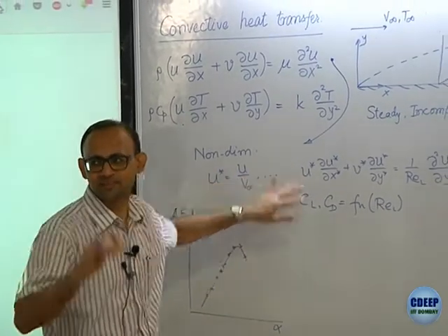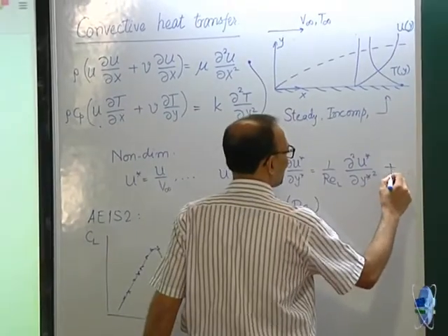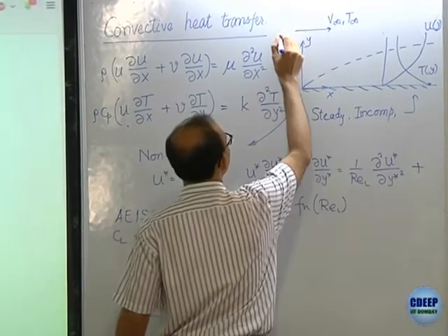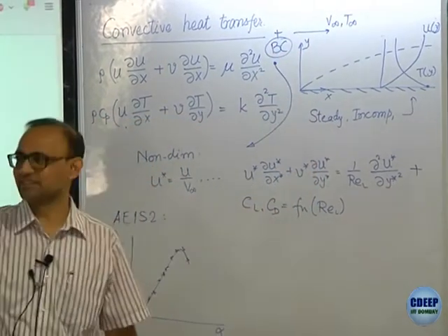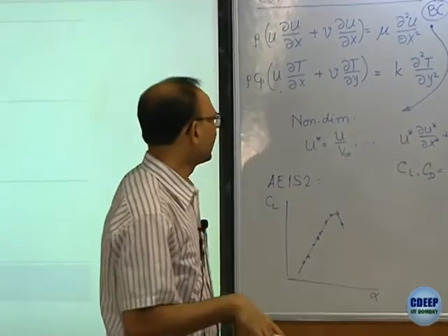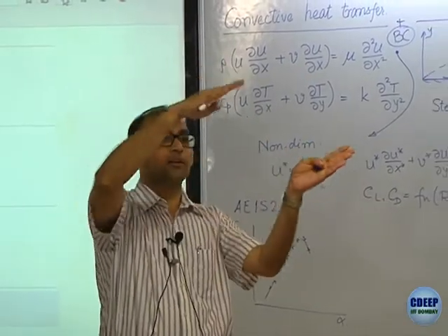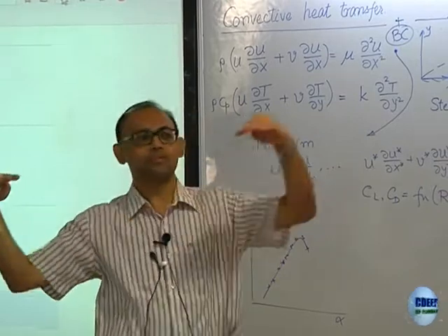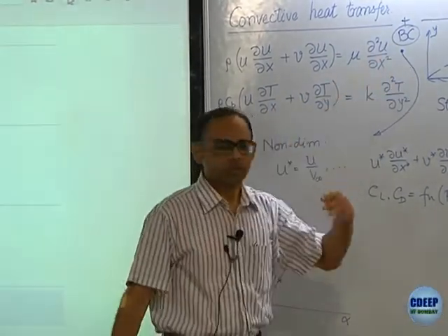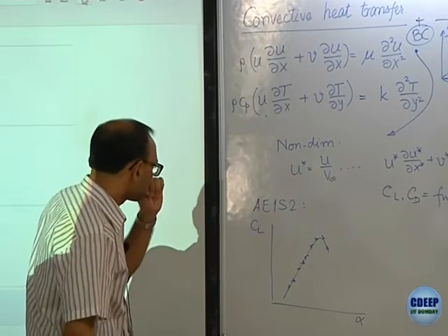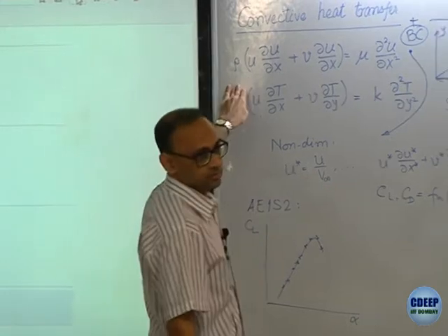Conditions, some conditions, yeah, boundary conditions. It's just a simple thing. So this equation or any of these equations plus boundary conditions. So boundary conditions is what brings in the geometry, which we didn't really say so clearly. If you have an airfoil, you match the shape of the wing that flies in the aircraft to what you test in the model and place the two at the same angle of attack. That is where the boundary conditions are coming in. So we'll apply the same idea to heat transfer.